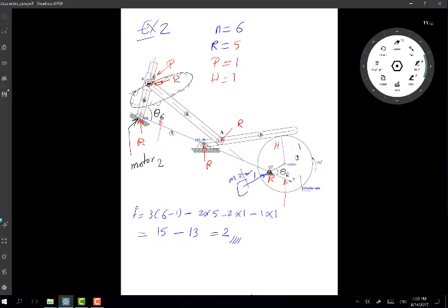Don't forget that if I want this to move on any trajectory, that's quite flexible in this case, because point B on the trajectory has X and Y coordinates, 2 degrees of freedom, and my linkage itself has 2 degrees of freedom, which are in fact theta 2 and theta 6, right?